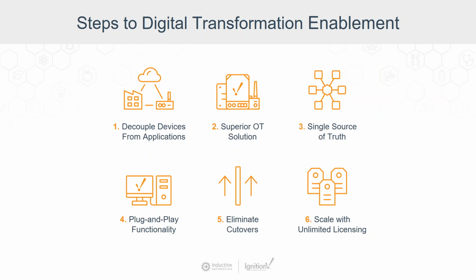And we also need, of course, a single source of truth. We can't continue to do mappings in every application: connect to the equipment, do a mapping for what tags are in there. Because if we ever have to change those things out, we have a lot of places to go and modify. It needs to be one place that's closest to the device where we define the information, the single source of truth of that data that we're going to bring up to our infrastructure and our enterprise.